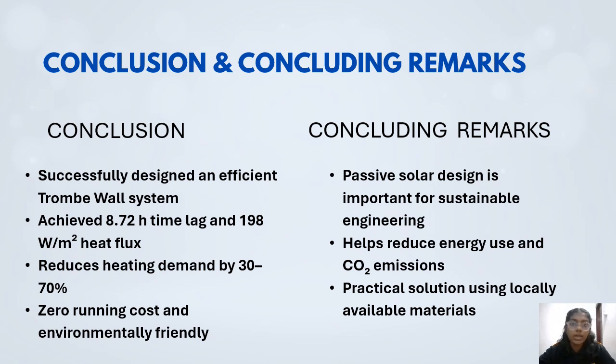To conclude, passive solar designs play an important role in sustainable engineering and energy conservation. Our Trombe wall system successfully demonstrates how solar energy can be used for indoor heating without relying on electricity or fossil fuels. The design achieved an 8.72-hour time lag, a heat flux of 198 watts per square meter, and a significant reduction in heating demand.